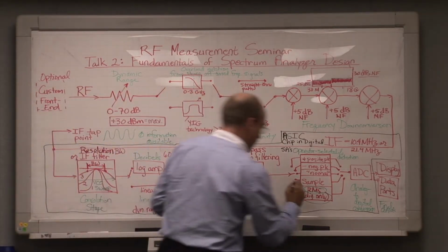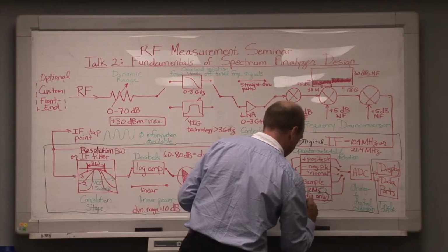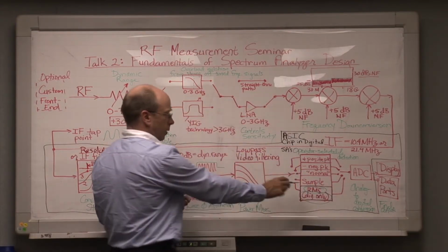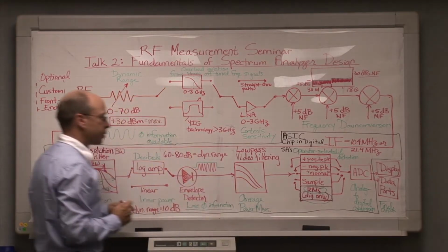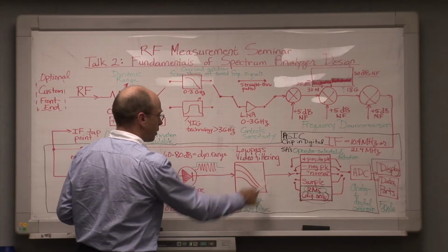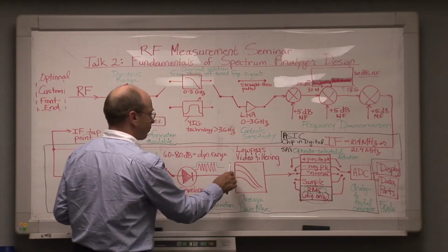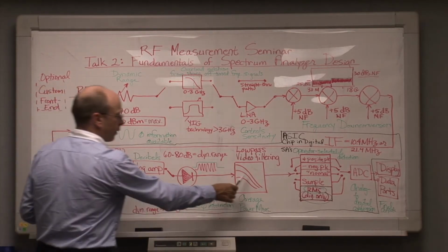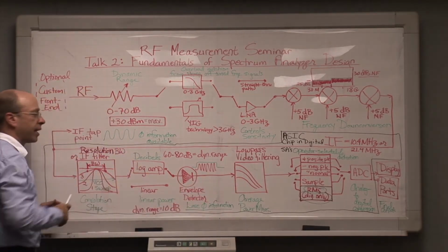The main difference being that the ASIC chip capability in the digital analyzer allows us to actually compute root mean square power averages, which are not otherwise available in an analog analyzer, where we have to use the somewhat less than ideal expedient of using a narrow video filter setting, narrow compared to the IF filter setting.